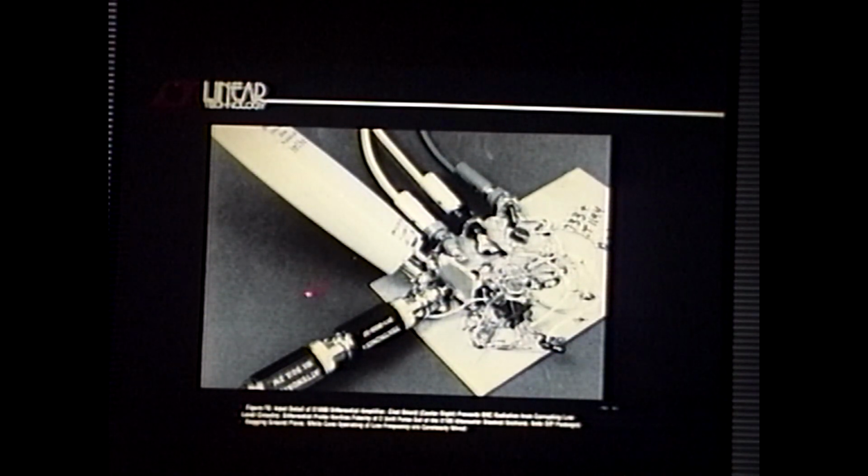In production, that's expensive. All of these breadboards presuppose that the object, when you breadboard, is to make the circuit work. To build this thing in production, you're going to have to do some thinking about layout. No floor manager wants to hear about shields like this. What you want to do is build the circuit so it works, and then start cutting stuff like this out to see what relative degrees of sensitivity to layout you've got. Battleship the thing first, then start cutting it apart to see where the sensitivities lie.